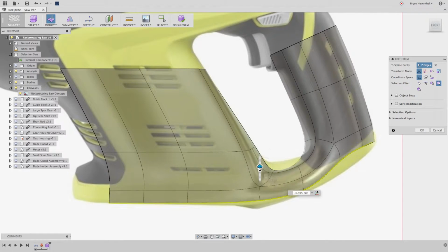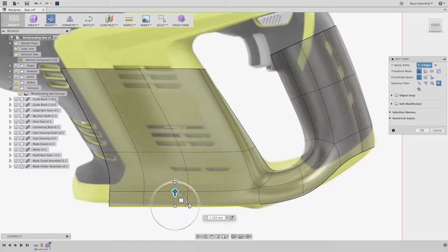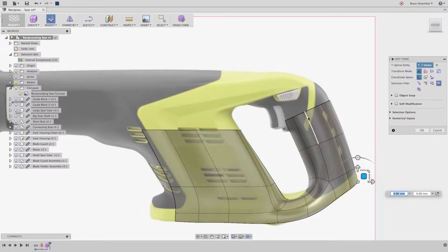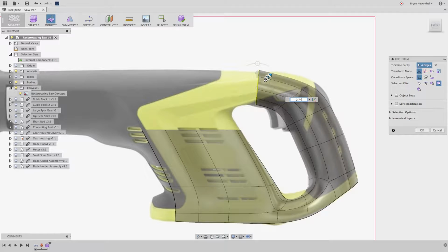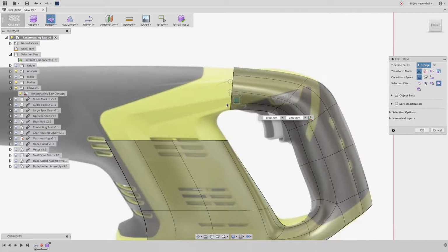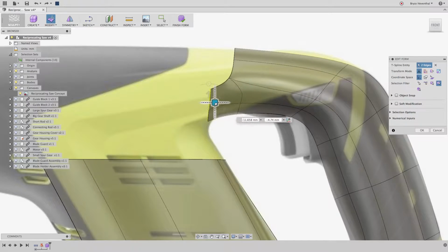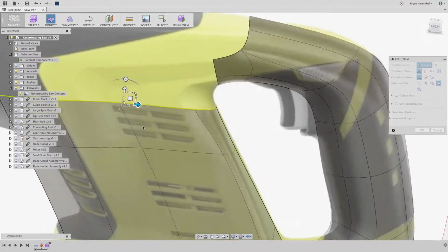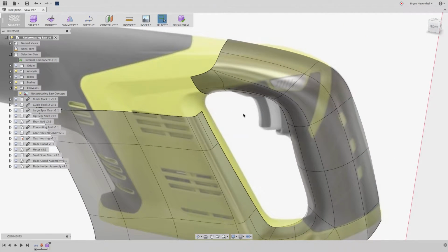In traditional CAD, I would be changing sketches, waiting for the CAD tool to solve the tricky loft or sweep, then hoping it didn't break any other feature. I will continue to use the same procedure on the top of this handle to get the desired transition. As the cylinder needs to navigate around this curve, I could rotate the edge loop to better match the curve. Again, I will add edges in areas of high detail when required.